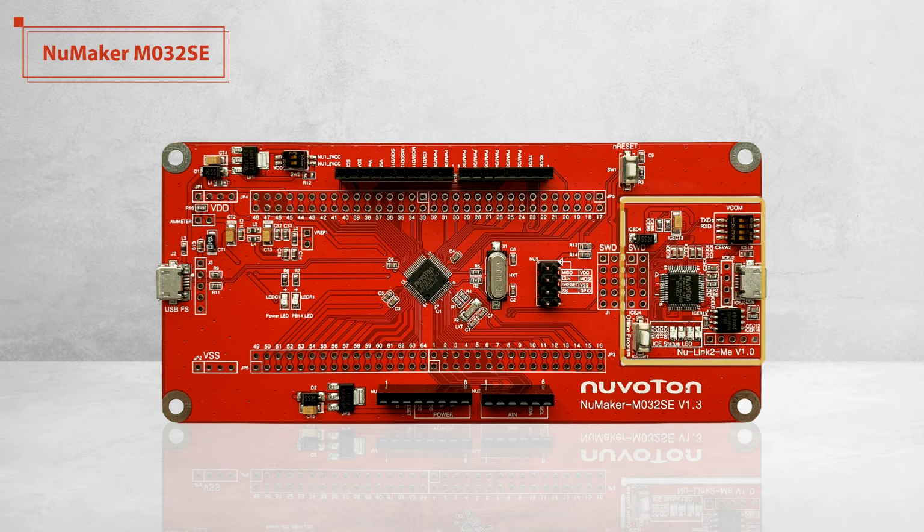Here it is. As a result, the only thing you need to connect the board to the computer is a USB cable. The type of debugger and programmer on the NuMicro board is the NuLink2Me. You can also find the version of it on the board. For other user scenarios, this NuLink2Me can be detached as a standalone debugger and programmer. However, there is no need to disconnect it in the exercise later.